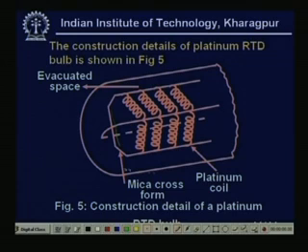What will happen is that if you put it inside a sheath and the temperature changes rapidly, I cannot measure it with this type of equipment. In that case I will simply use something else. So it is not much used for dynamic measurements; it is used for steady state measurements or very slowly varying temperature measurements, not for rapid measurements.